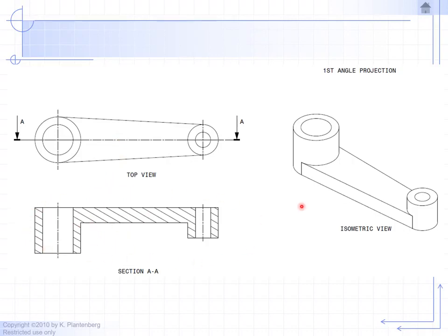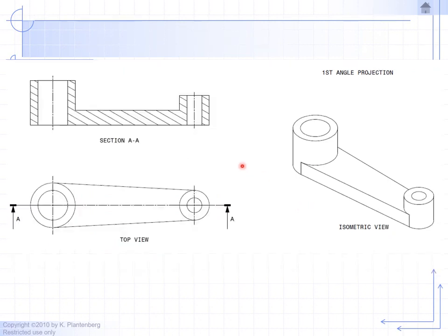Let's take a look at another example of first angle projection. Next slide. Here's another option you could have had using first angle projection. You have, in this case, your front view, and you can call this your top view. It doesn't really matter. Okay, so in this case, the arrowheads are pointing upward, keeping the top half, and projecting upward.